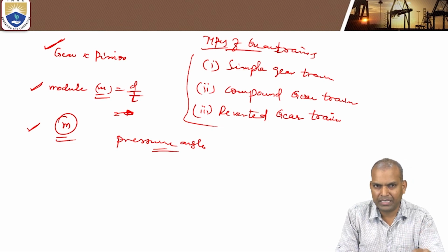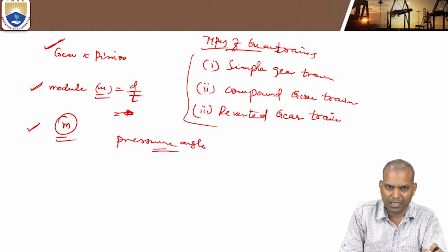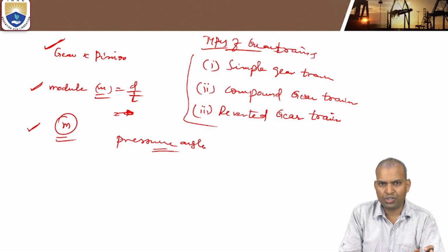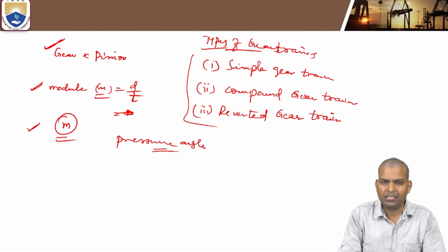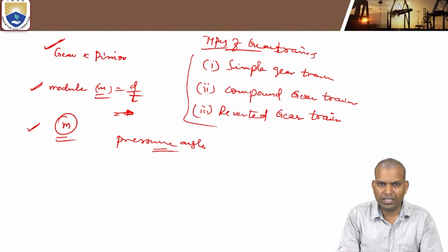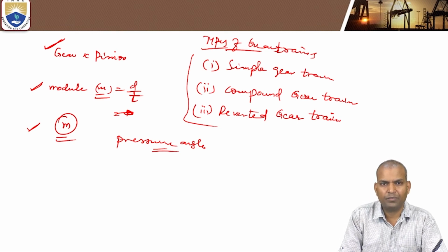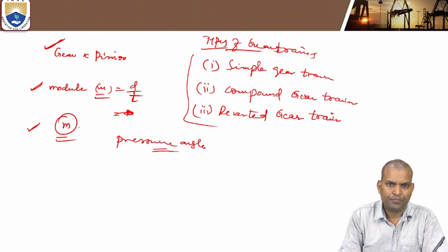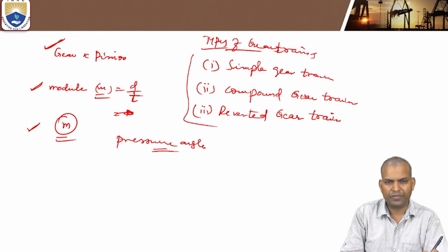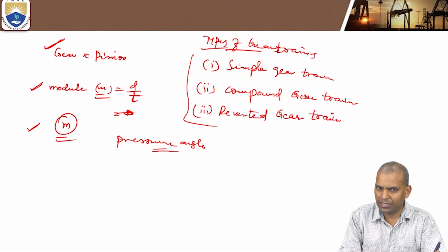Here gears are different; gears are not a train. They are single types of gears based on shafts. If the two shafts are parallel, those come under spur gears, rack and pinion, and by helix angle, single helix, double helix, and herringbone gears. The intersecting shaft gears are straight bevel gear, spiral bevel gear, and zero bevel gear. Spiral bevel gears are used in the differentials of automobiles.